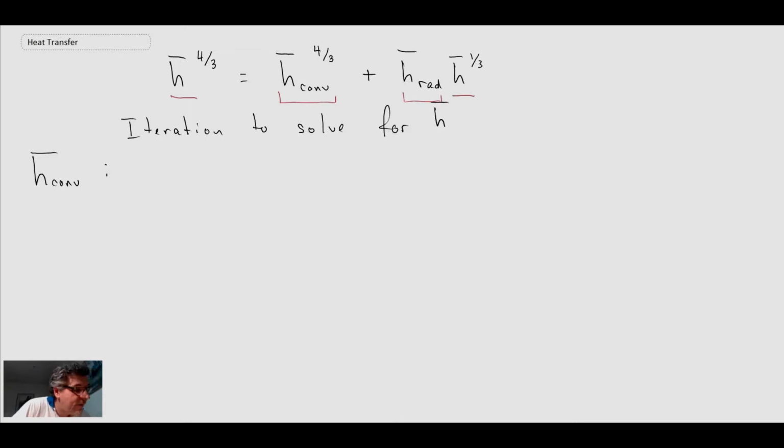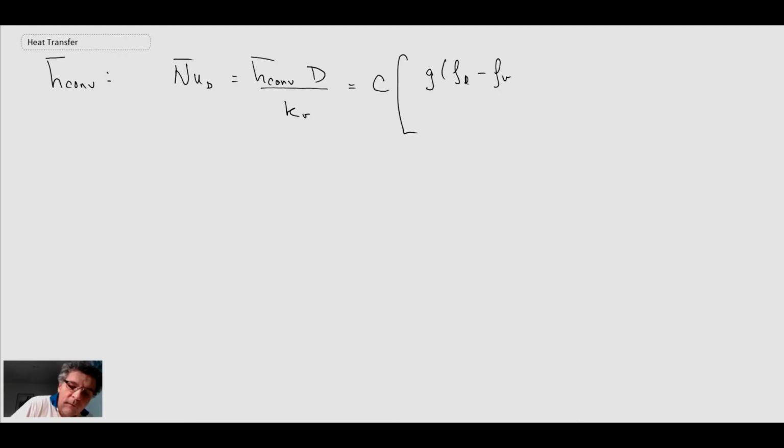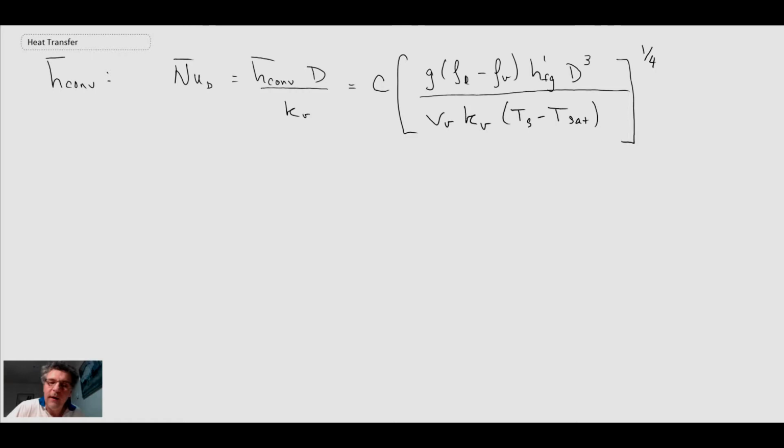And for this, we have a Nusselt number. And you know what I'm going to do? I'm going to put it on the next slide just because I'm running out of space here. I don't want to have it all in one space. There we go. Okay, so very similar to the other expressions that we've seen for q max or even in nucleate boiling. But it's a little bit different, and first of all, this equation applies only to certain geometries.